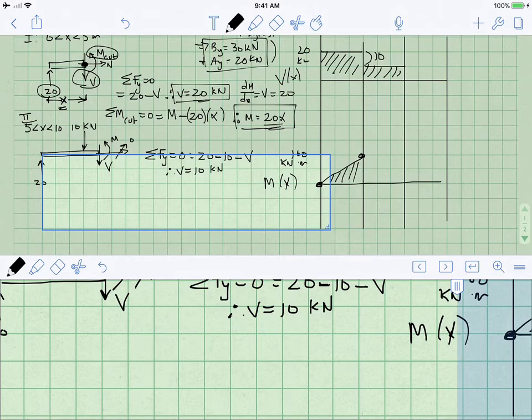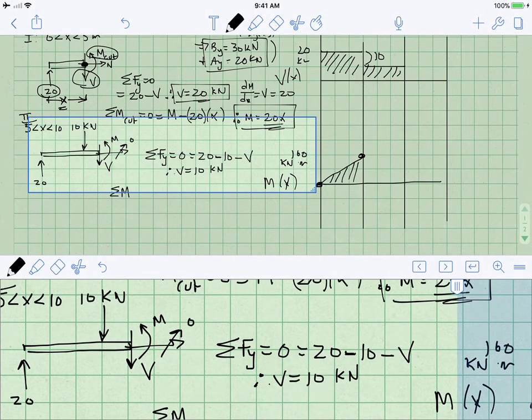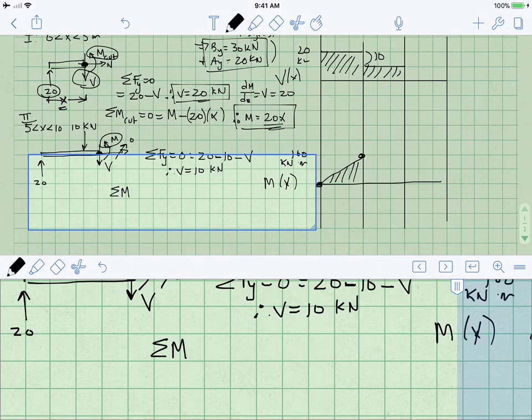Relative to moment, again, we are in equilibrium, so we write, and we're thinking about here, right? This is our mental position. Our objective is to find that M, which is the bending moment, present in that particular segment of the beam. So again, this beam is in equilibrium, so the sum of the moments at that cut point is going to equal 0, and that is going to equal this unknown moment that we're trying to find.